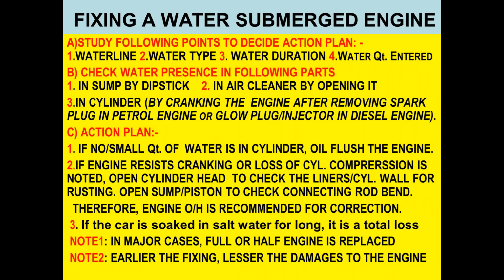Fixing a water submerged engine. How should we fix up a water submerged engine? There should be a proper plan for it. First, you study the following points to decide the action plan. Water line means the water level up to which the vehicle was submerged. Then the water type, what type of water, the water duration, how long it was in water, and water quantity entered into the engine.